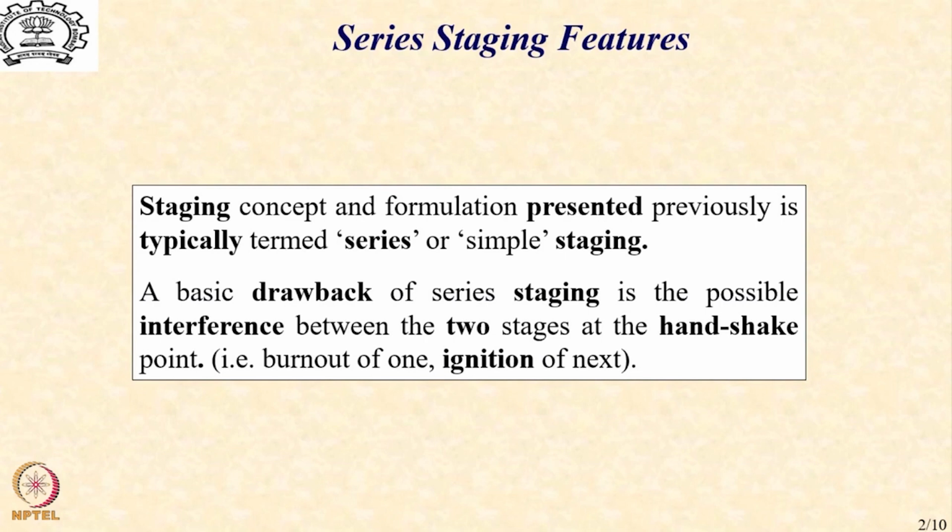And this particular point becomes an extremely critical point from operational perspective, that how do we ensure that the stage which has completed operation is removed with as little disturbance as possible, and the stage which is supposed to operate starts without any significant delay, because during this period, as you would immediately realize, there will be no propulsion on the vehicle, and that is something which may not be a desirable objective, particularly when you are in the lower atmosphere where there could be disturbances that might affect its overall performance.